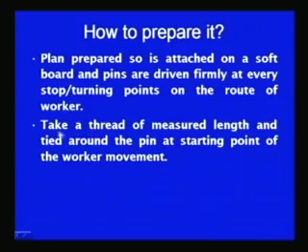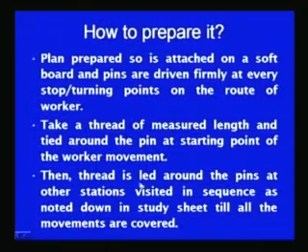Then a thread of measured length is tied around the pin from where the journey is started by the worker, and after that the thread is led around the pins at other stations being visited by the worker in sequence, as noted down in the study sheet, till all the movements are covered.